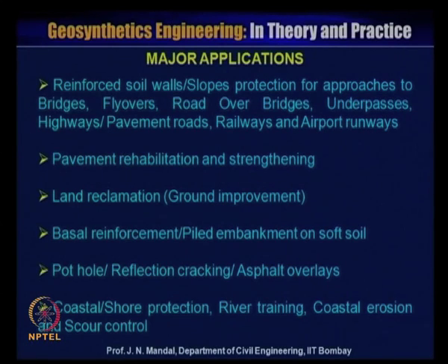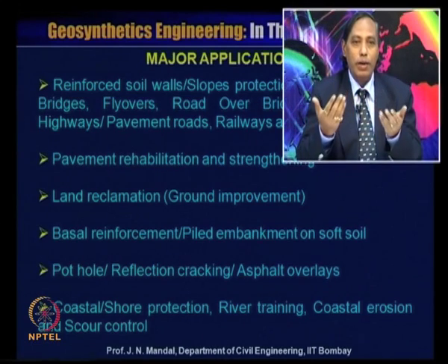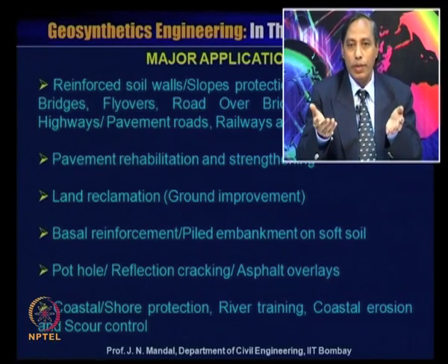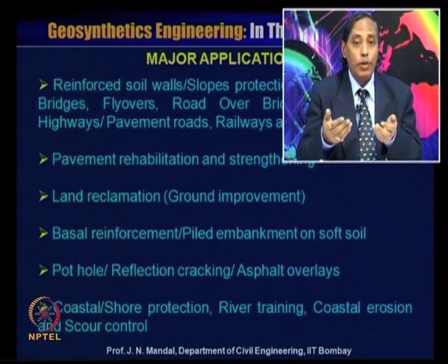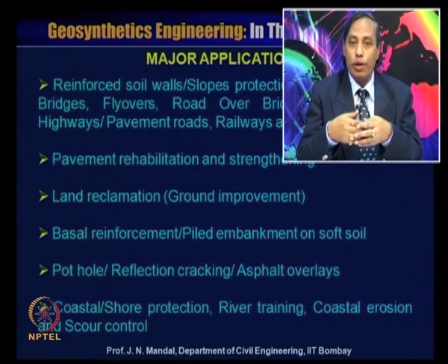You can do pavement rehabilitation and strengthening, land reclamation, and ground improvement. When the soil is very soft, it is very difficult to construct any kind of structure. How can you improve the ground using this new material, the geosynthetics? Basal reinforcement, pile embankment on the soft soil.